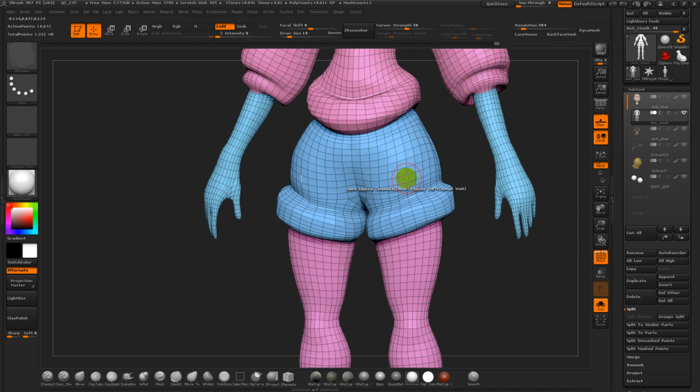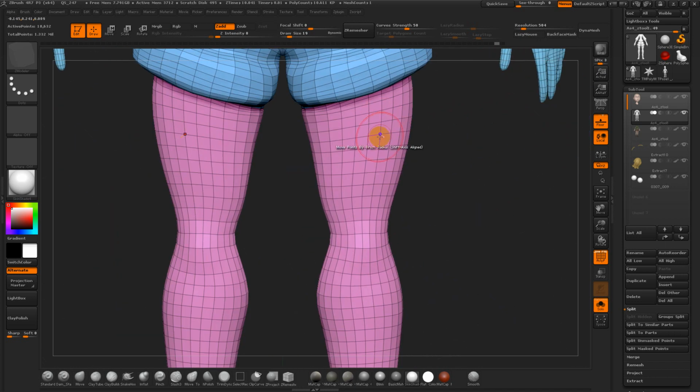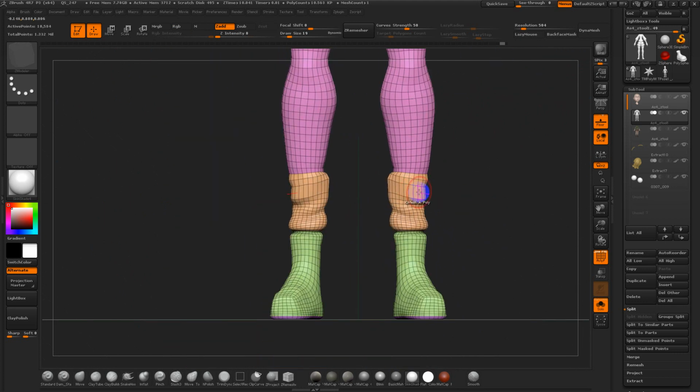Sometimes when I'm testing for looping or spiraling, which ZBrush can do, it's okay if it does this crisscross. Can you guys see this when I click on this loop, or maybe this loop? Sometimes it might go through the inner leg or something. That's not necessarily a bad thing, but it's when it spirals, meaning it goes down 3, 4, 5 times as a continuous loop, that you'll want to avoid. Just because for UVs, if you try to find a seam, or try to do something else with it mesh-wise, it's going to be a nightmare.